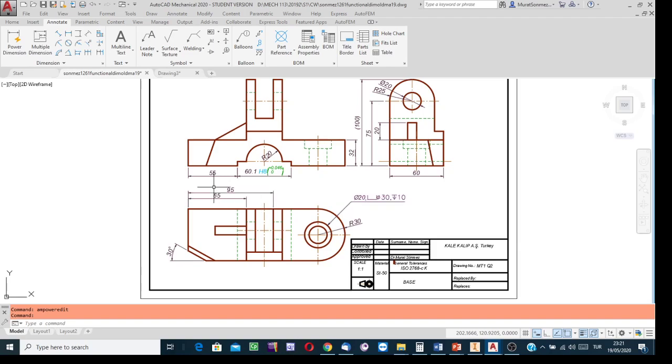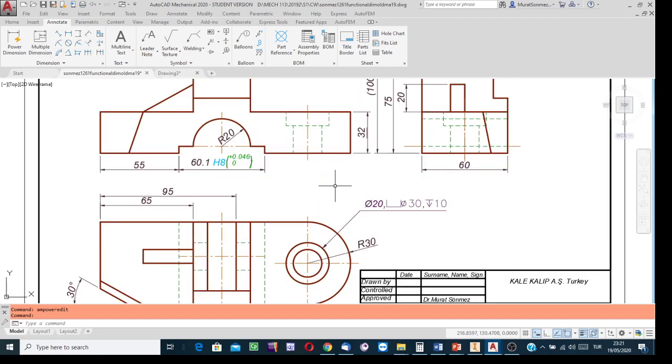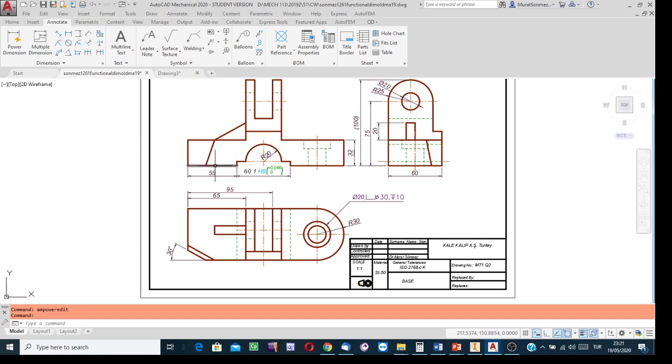At the beginning in AutoCAD, it is recommended, considering how many dimensional rows you're going to have, to have the space between the views sufficiently large at the transfer line creation stage. But if you couldn't foresee that you will show one more dimension or a few more dimensions, so at the beginning you made a mistake and couldn't have the space sufficiently large, what can you do?